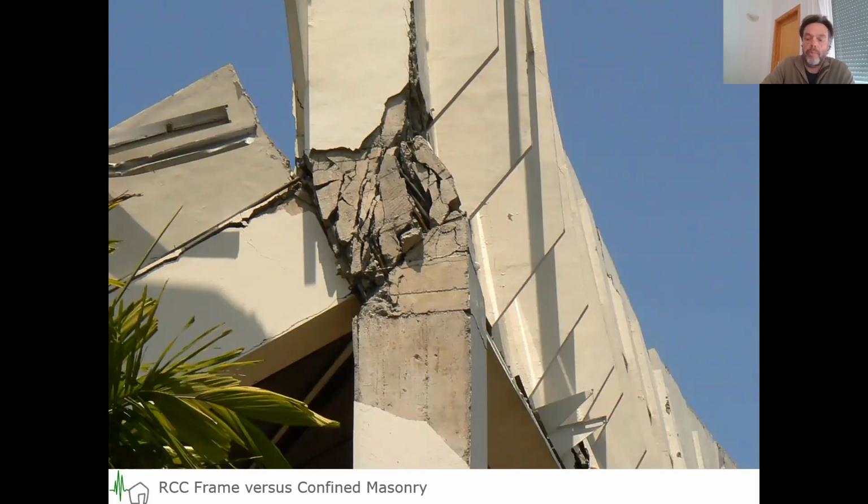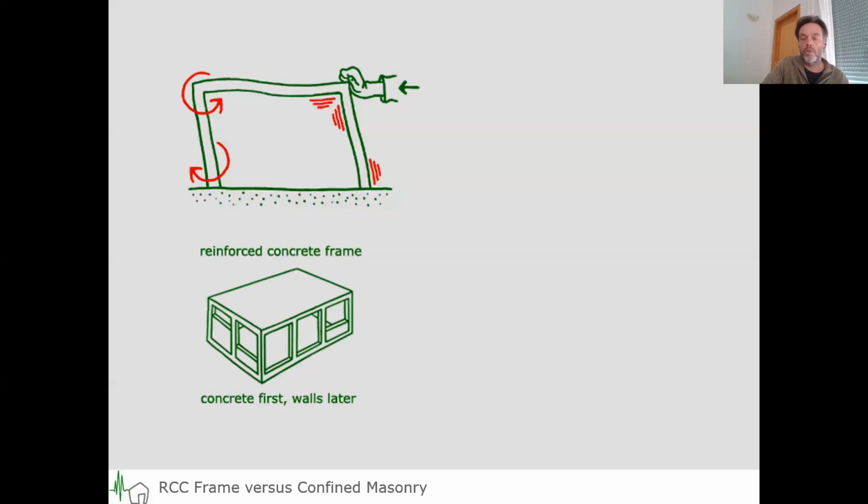This is a picture from the Pariaman earthquake in Sumatra in 2010. You see here what happens when it is not properly detailed and the quality of the concrete is too weak. But there are two things happening here, because the frame that wants to bend and dance is usually filled up with a very stiff plane of masonry.